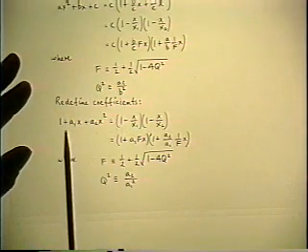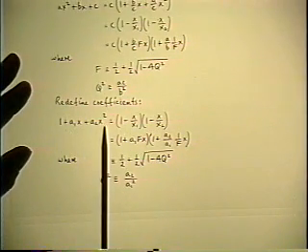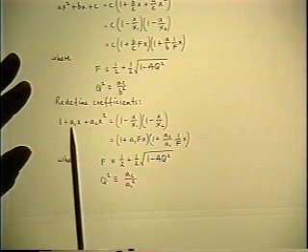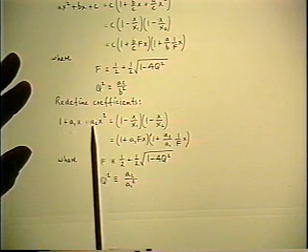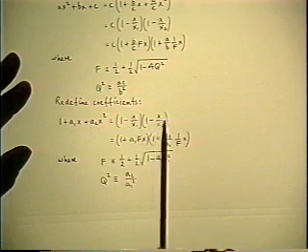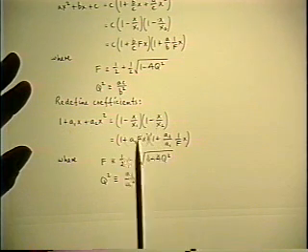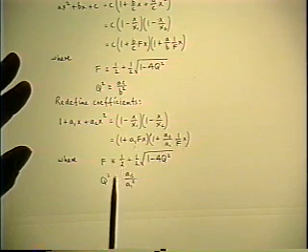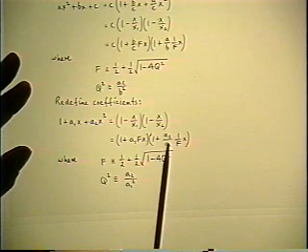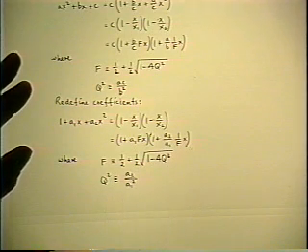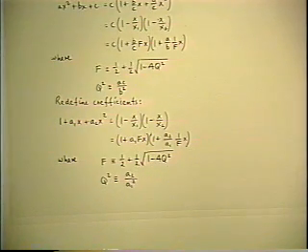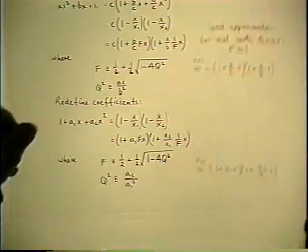here's the quadratic with ascending powers of x, or complex frequency, with appropriate coefficients in terms of circuit elements. Here are the factored format in terms of two corner frequencies, and this is what they are in terms of the A1 and A2 parameters instead of the original ABC. Simply an alternative format.